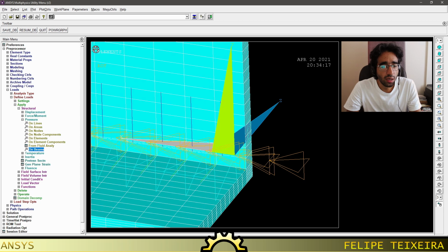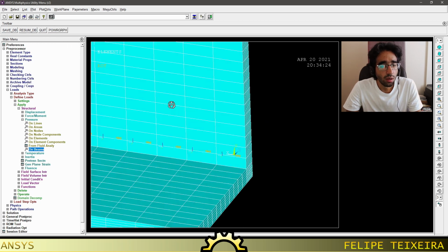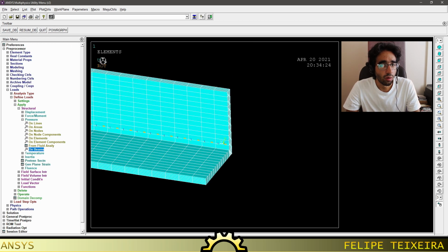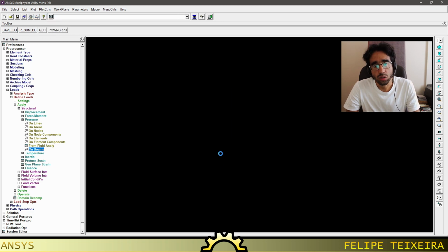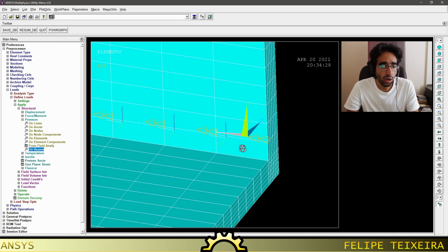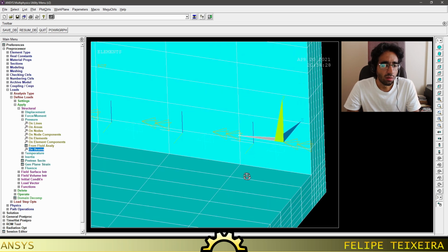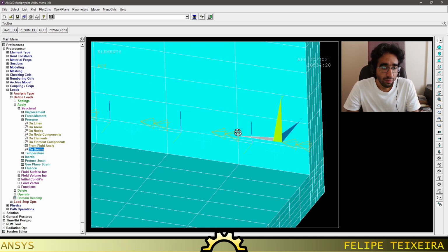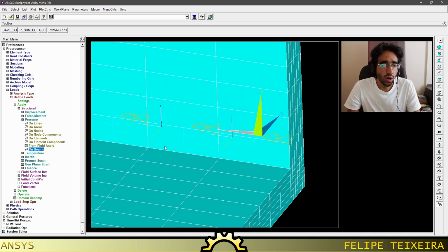So I'm going to zoom to the beginning of the beam so we can simultaneously look at two things: local axis for a few of the elements and the global XYZ axis. This is what you're seeing here. As you can see, ANSYS uses white for X-axis, green or yellow, I don't know, for Y-axis, and blue for z-axis. That's the color scheme. So the global triad is indicated there, XYZ. The other axis, those thinner, smaller axes that are appearing at the centroid of each element, are the local axis of that element. And the color schemes also apply here.